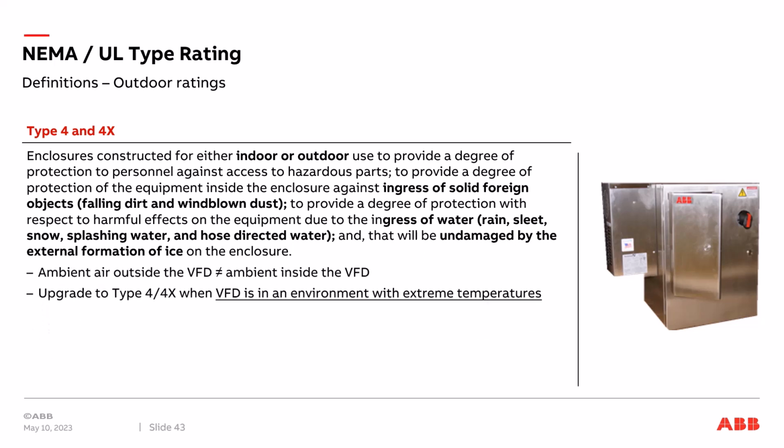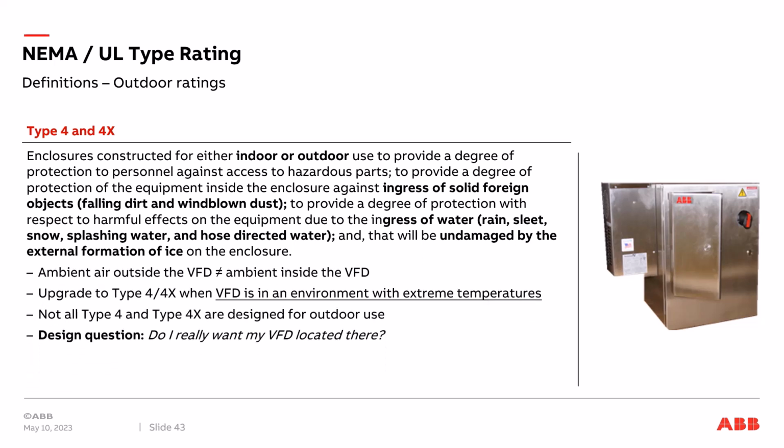The ambient air on the outside is not equal to the ambient air inside the enclosure. You can upgrade to Type 4 and 4X when the VFD environment is extreme temperatures. Not all Type 4 or Type 4X designs are for outdoor use. Sometimes they're only for indoor use. It depends if they're designed for sun loading. The real question you have to ask yourself is, do you want to put the VFD where the location requires a 4 or 4X enclosure?